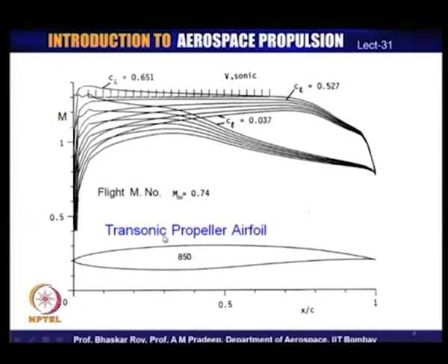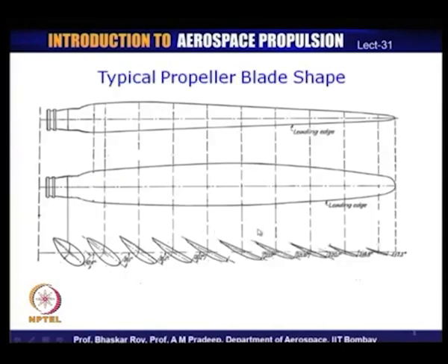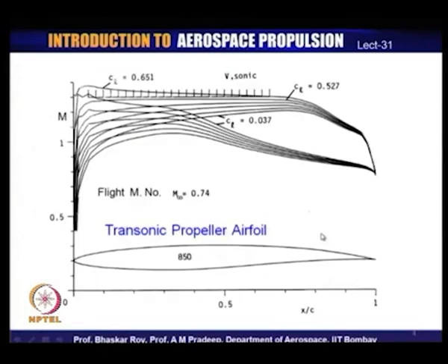Now, this kind of transonic aerofoil is typically used in the tip area, where we were earlier using very thin aerofoils to conform to a high subsonic flow. This is the area where flow is now likely to go transonic in the modern propellers, and instead of these thin subsonic aerofoils, the modern designers would like to use such transonic aerofoils, where the local flow, the combination of forward velocity and omega r, that is the rotational speed, makes the flow actually go supersonic over the aerofoil shape.